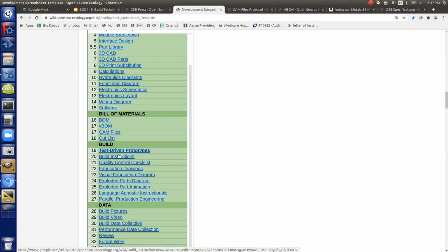hydraulic gear down and put it on a measuring device, or make a measuring device to see, okay, how much torque do you have? Or just take data like over 5 hours it heats up like this and then stabilizes, whatever. Take data. That's all data that's relevant. Instead of building the whole machine and then waiting, okay, we're just going to field test it, you can get data for individual parts, and that's called test-driven design. It's a very important part of a formal development process because then once again, with the modularity concept, you're not waiting till you have the whole thing and then you've spent all that energy doing it.